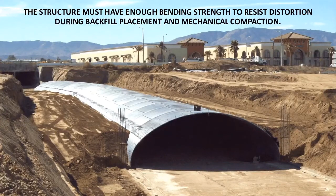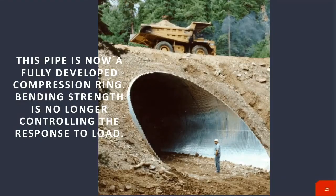So again, you need to have the inherent ring stiffness and bending strength of the pipe wall profile to resist those deformations. But then once you get fill up over the top of the structure to the minimum cover level, the pipe will act as a ring compression structure, and again can carry very high heights of cover or very large vehicles, such as shown in the mining equipment crossing over this structure.